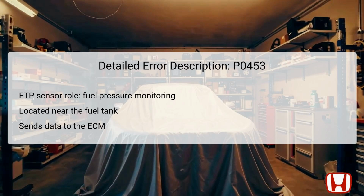The error associated with DTC P0453 involves the fuel tank pressure (FTP) sensor, which plays a vital role in monitoring the pressure of fuel vapors within the fuel tank. Positioned near the fuel tank, this sensor continuously sends pressure readings to the engine control module, ECM, facilitating accurate fuel management and minimizing vapor emissions.